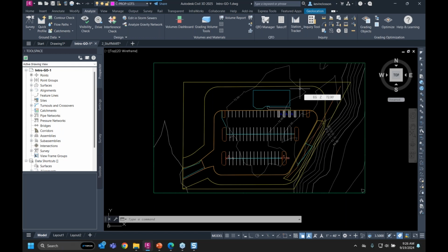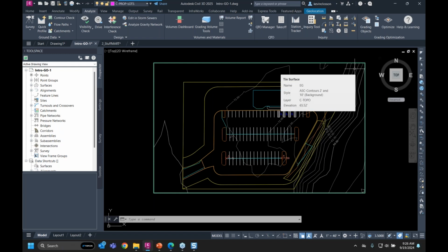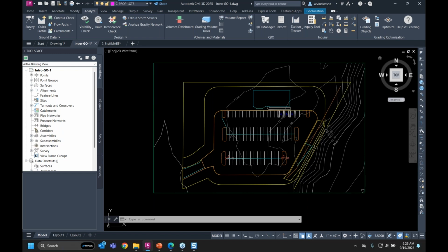Okay, and then, just like I was mentioning as I was looking at this drawing here, we also have to define a boundary of the grading limits. And that's what I'm looking at back here. I'm not sure what kind of shape that is, but you can see that's the overall extent, okay? And then any additional line work, building pads, curbs, drain lines, all of that's going to go into that drawing as well. When we put in those kinds of key lines, those are going to be more of a constraint rather than an objective. They just have some different terminology in there.